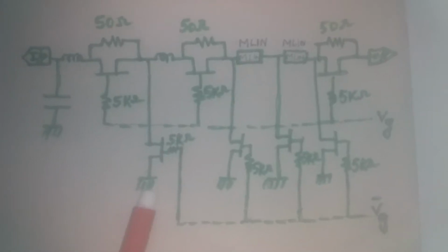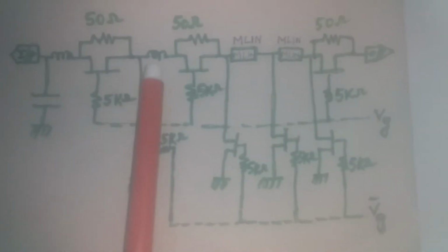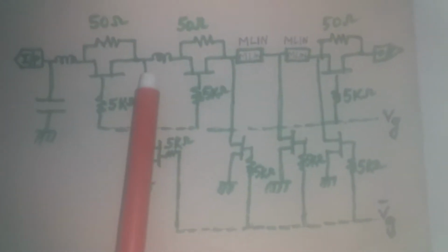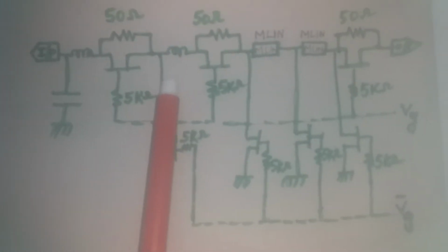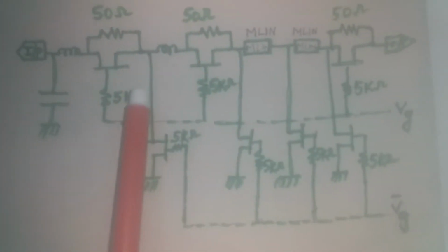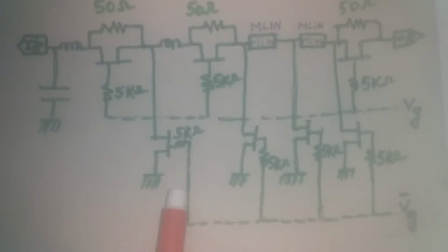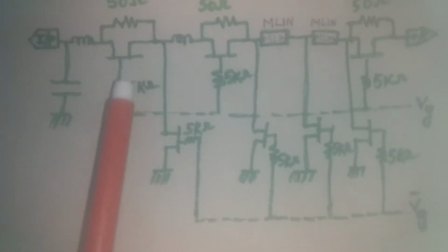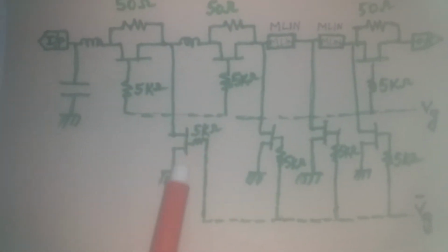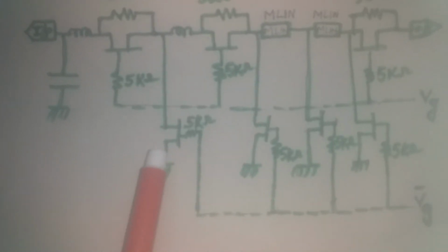And the shunt FET CDS is used to form an artificial 50 ohm transmission line with the addition of a series inductor. So this configuration not only improves insertion loss but also ensures good return loss over full bandwidth. The series FET improves isolation at low frequencies, which we have seen, okay, and this improves isolation at high frequencies, that also we have seen.